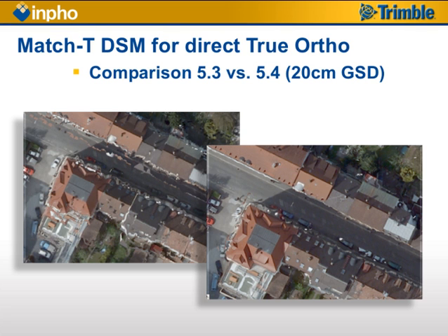And just keep in mind, I wasn't doing any editing here. I just used all the results like they're coming out of the software without any manual interaction. And also keep in mind that this product is derived from a 20 centimeter photo flight. Considering that our new cameras available on the market are able to capture ground sample distances of 3-5 centimeters, this result for direct true orthophoto would be extremely good.